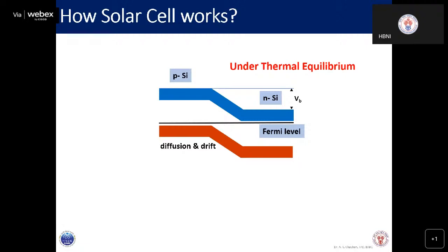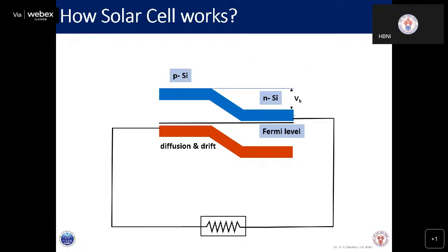So now we take contacts at two ends. Now can we take this contact? I just want to know, because we discussed yesterday also, when this contact is of metal, when we fuse a metal with the semiconductor, there will be a Schottky barrier. Because of that, it will also behave like a rectifier. Similarly, here also it will behave as a rectifier. So these will actually be two back-to-back rectifiers. So there will not be any current.